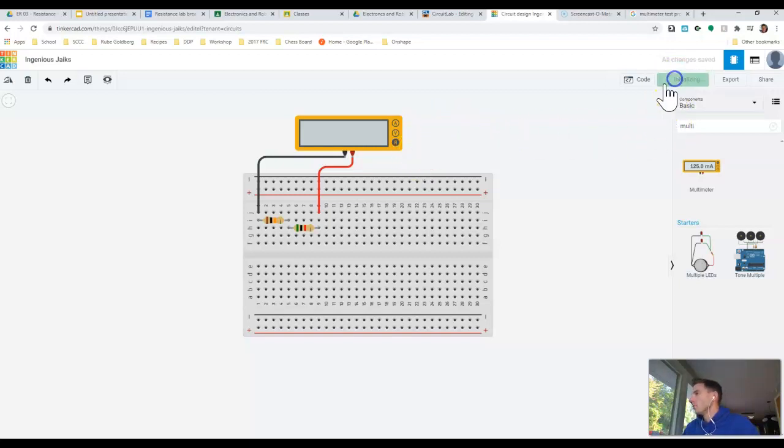So when I start the simulation at the top here, we now start to measure its resistance, and we are going to measure a perfect 15 kiloohms. Now in real life, there are tolerances involved in these resistors, and in real life it would measure anywhere plus or minus 5% of this. So it might read somewhere in the high 14,000s or maybe the low 15,000s. On the simulator, that's always going to read exactly right. So that's how we measure that.